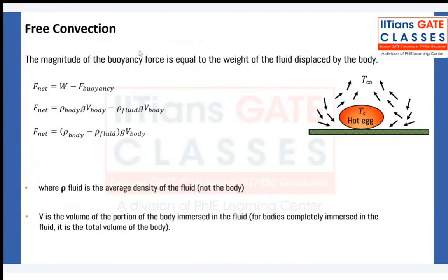Okay. Chalo. If, for example, this is a cold plate, so fluid will come like this. It will move down because its density is going to decrease. I'm sorry, increase. If this is a cold plate, so T surface is less than T infinity. So fluid is going to come and give some heat, becomes colder, and its P upon density is equal to RT.